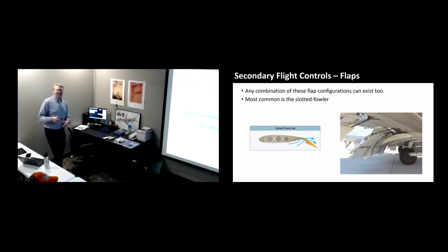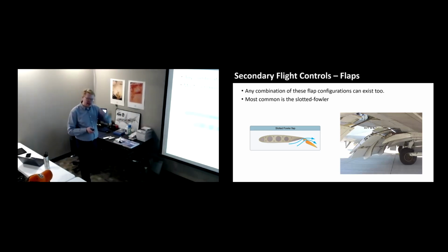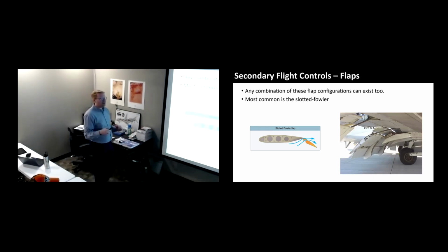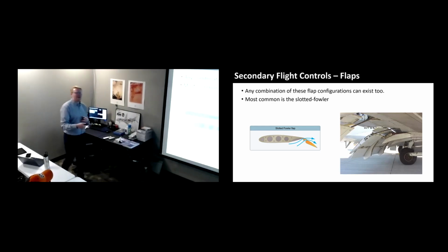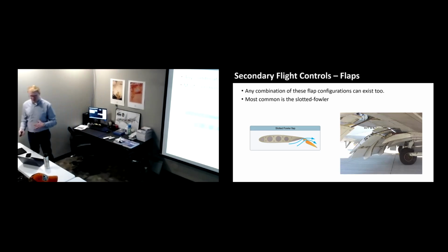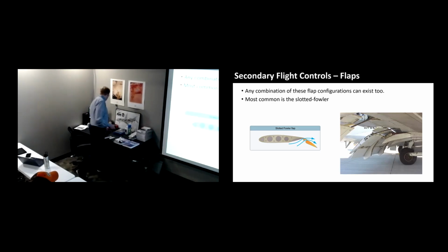The heavier you get, those wing designs that an airliner would fly on, they're really not designed for slow speed flight. That's not their design. Like we said, a Piper Cub has a wing with a big camber over the top that produces a lot of drag. Airliners are designed to produce a lot of lift at high speeds to move fast. Those wings aren't designed for slow speeds. There's a bit of a trade-off you have to make. So to fly at slow speeds, these are the guys that have a ton of flaps. Airliners will see a lot of flaps. Our airplanes are designed for slow speeds, so flaps aren't the most important thing in the world, but we'll use them all the time. You'll get to see their impact quite a bit. Any questions on that?